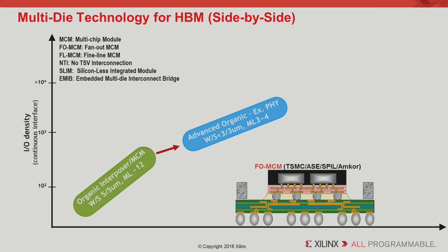But if you can extend that technology, what you do here is you take known good dies, and these are reconstituted on another wafer format through a molding process. And then this wafer goes through subsequent steps to create these RDL layers that are built up on top. So this is what you would call an RDL-last approach, because essentially you are taking known good dies and then doing quite some intensive post-processing with it.